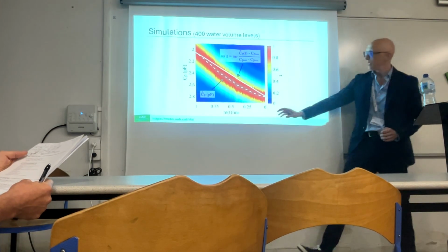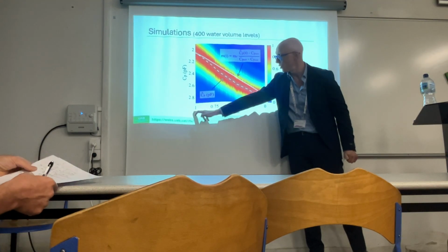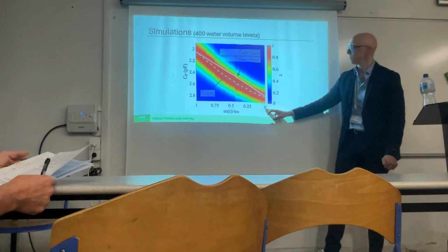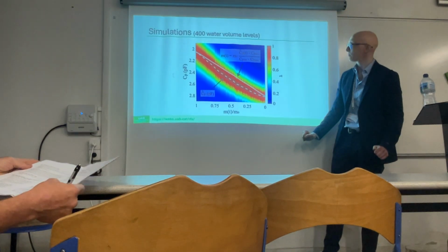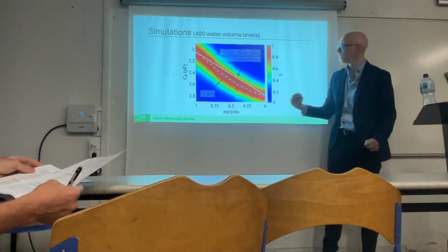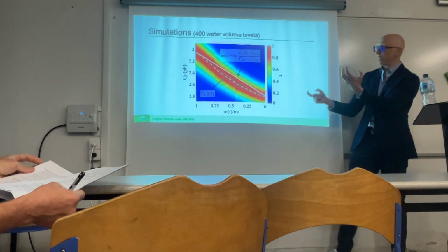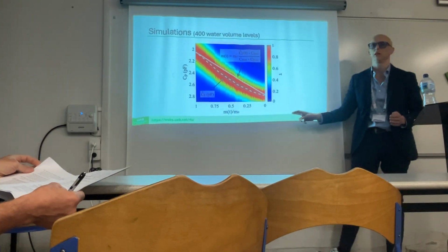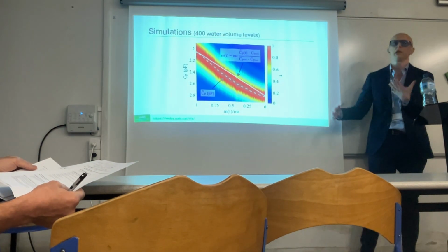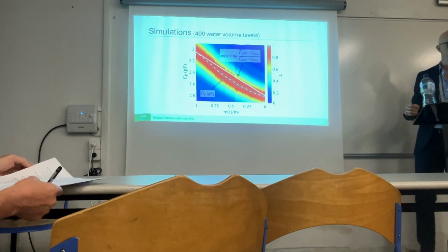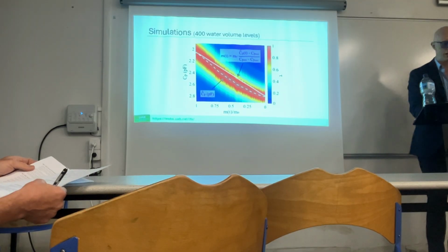As you see in this figure, I'm showing the water going from 100% to 0%, and the capacitance range in the vertical axis. So this white dashed line gives us the capacitance that the chip will select for all the different levels of water. And the continuous line is a linear model that we will use later on for transforming the sensor code into the mass, the water mass loss.